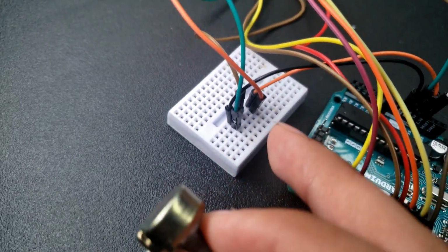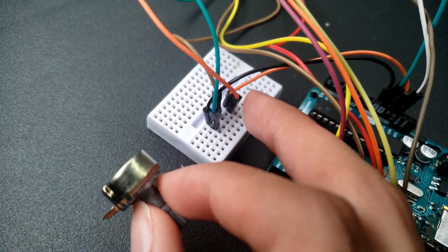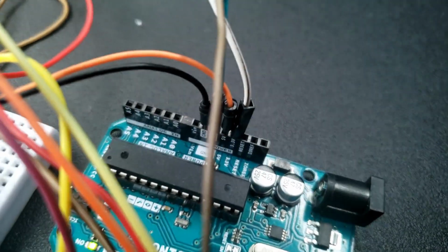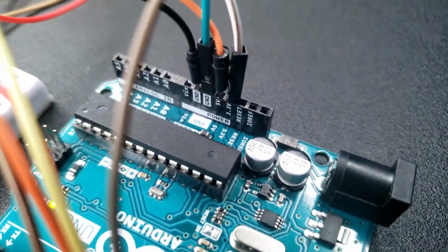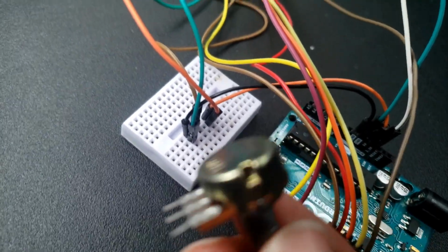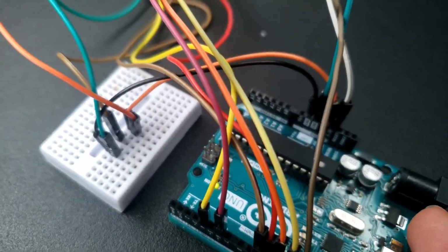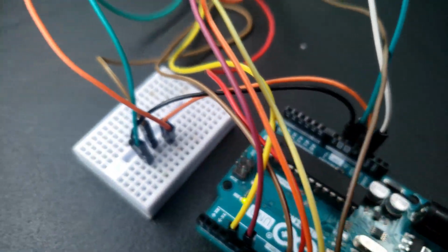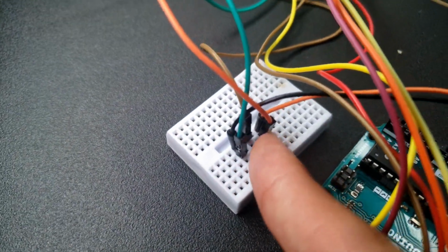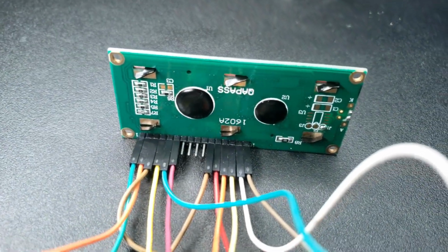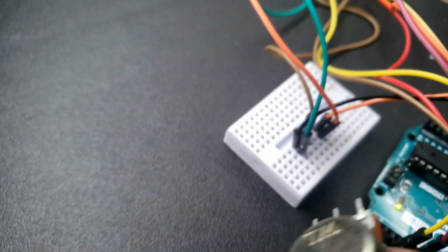Then the one all the way over here, it's both lined up, orange and orange, and see this one right here, it's connected to your actual power of like 5 volts, because you need 5 volts for this potentiometer to work properly. You could actually use another one, like you could have used the 3.3, but you can see that's already occupied. Anyways, and then right here, the middle one, it just goes straight to your display. And that's how it works.